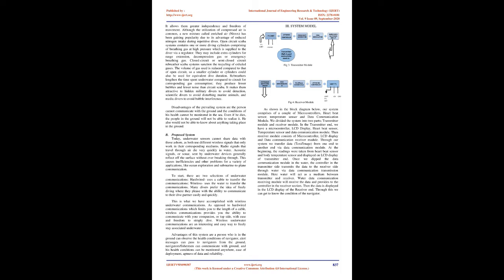Open-circuit scuba systems contain one or more diving cylinders containing breathing gas at high pressure, which is supplied to the diver via a regulator. They may include extra cylinders for range extension, decompression gas, or emergency breathing gas. Closed-circuit or semi-closed circuit rebreather scuba systems allow the recycling of exhaled gases. The volume of gas used is reduced compared to open circuit, so a smaller cylinder or cylinders could also be used for equivalent dive duration.